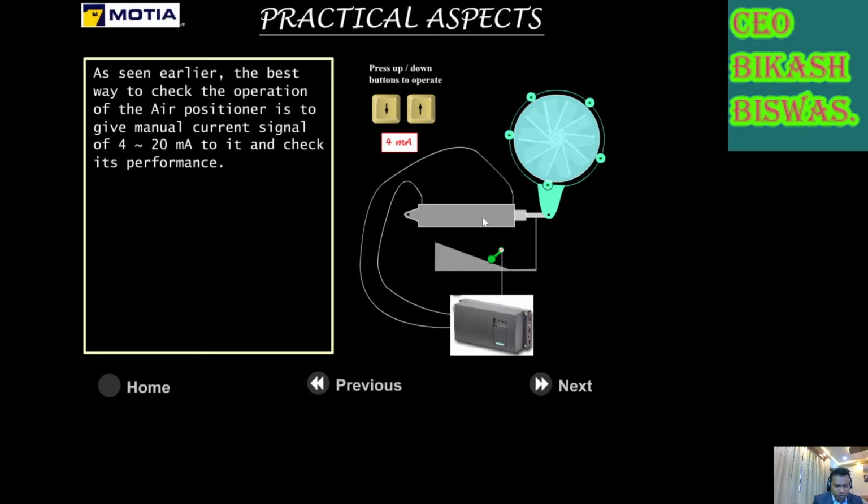Servo air alarm is that when you fire the boiler, there are some sequences and some positions: the ignition position, then the firing position, then the post purging position. In these positions, your air pressure has to be within the range with the air fuel ratio. If it deviates more than 10%, it will give you a servo air alarm and your boiler may get tripped. So it will lead you to an emergency situation. And if the troubleshooting takes so much time, there will be delay in discharging and the ship may be off-hired, and there will be immense pressure from the charterer, from the owner.